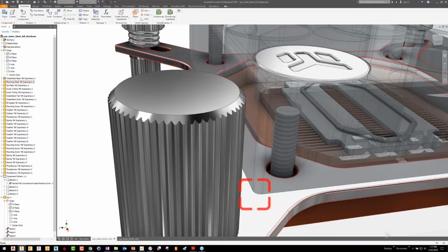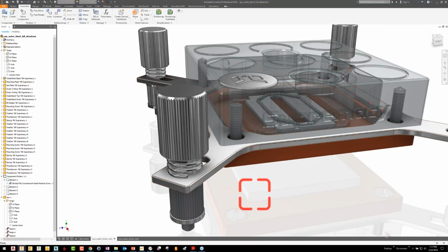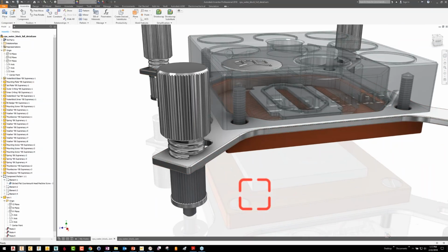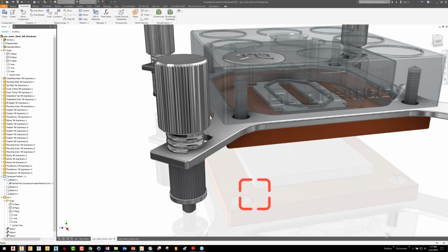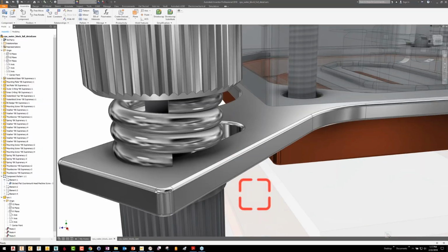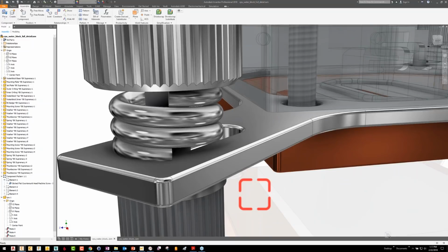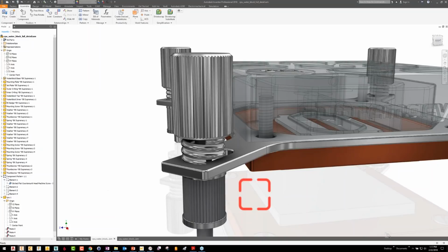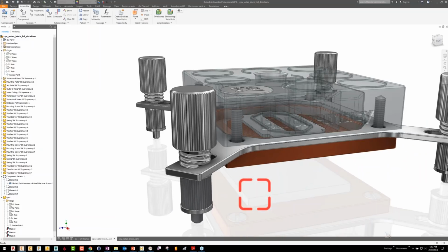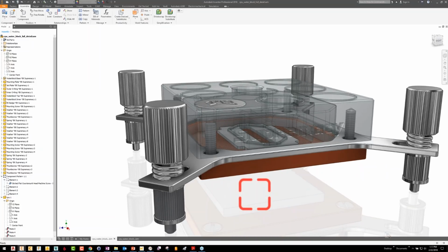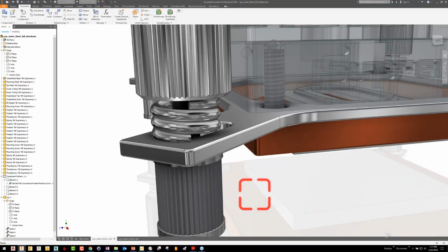And in fact, in this particular model, I removed the screws altogether. And those are going to be replaced by a force. The springs themselves are actually pretty complex FEA problems if you've ever tried to design a spring, and people do. That would be a case where you'd want to mesh a spring in 3D and actually analyze it. But if it's just part of a larger system meant to impart some stiffness in the model, well, you're not going to include that. You're going to exclude that and replace it with an element that kind of approximates a spring. And you'll see me do that too.